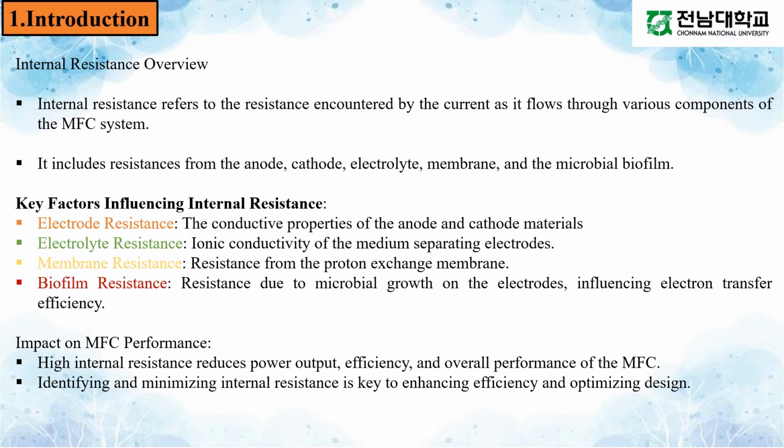The key factors which influence the internal resistance are electrode resistance, the conductive properties of the anode and cathode materials; electrolyte resistance, the ionic conductivity of the medium separating the electrodes; membrane resistance, the resistance from the proton exchange membrane; and biofilm resistance, the resistance due to microbial growth on the electrodes, influencing electron transfer efficiency.